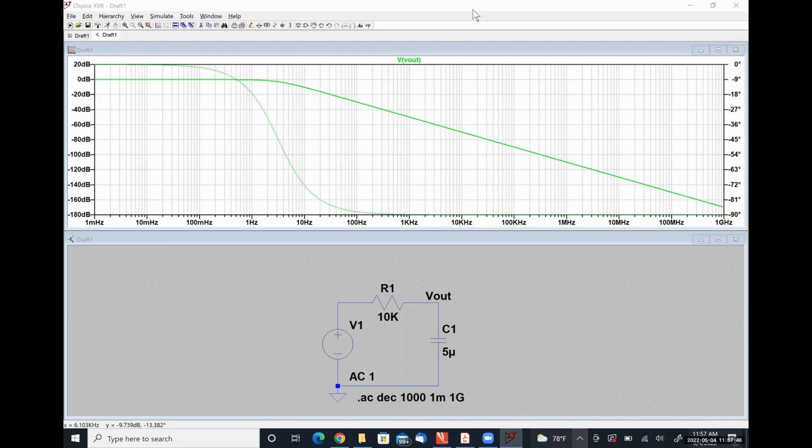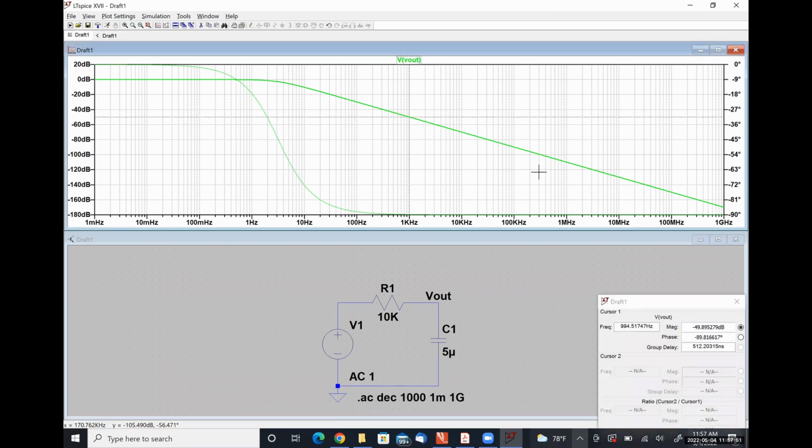How we would do this more specifically, measure things, is if we click on this, we get a slider that we can use. So because we are using passive filters, our voltage gain literally can never be larger than 1, which corresponds to 0 decibels, okay? So our cutoff frequency is then going to be whatever frequency our magnitude hits -3 decibels.